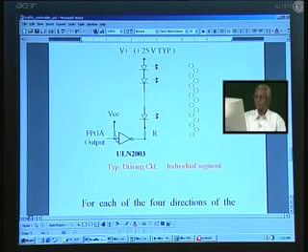And if you go for the higher size display, for one segment you need this group of LEDs, and they are all cascaded and shown here as a series connection. Note that when an LED conducts, it will take up approximately 1.5 volts. If you put 15 of them, naturally it calls for 22.5 volts.